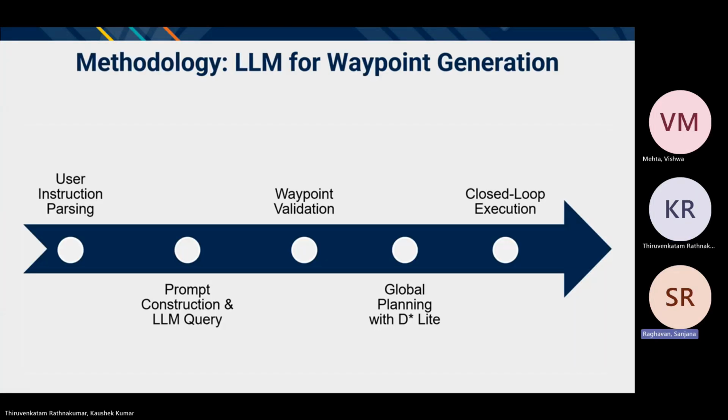In this slide, I'll walk through our LLM-based navigation pipeline. The process starts with a high-level JSON command that specifies the source object, target destination, and any safety constraints like obstacle margins or waypoint spacing. We pass this command alongside the robot's current pose and the semantic map, which includes labeled object landmarks. These elements are embedded into a structured system prompt that also includes the occupancy grid map.